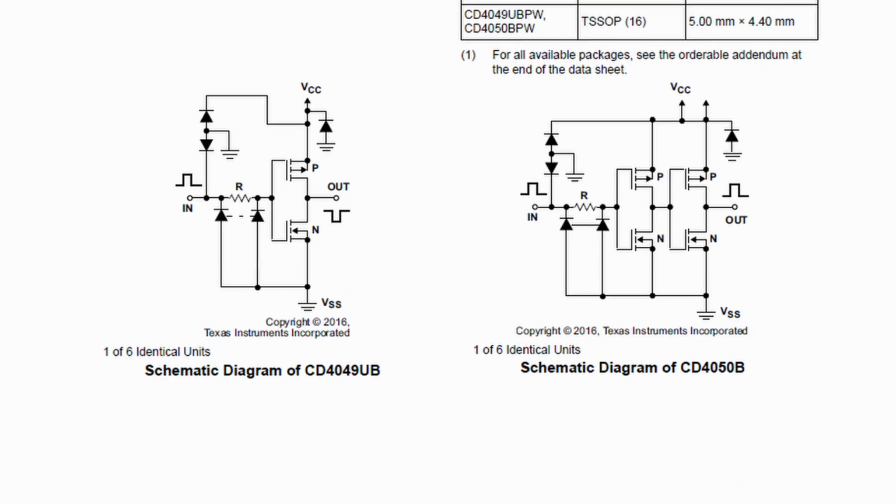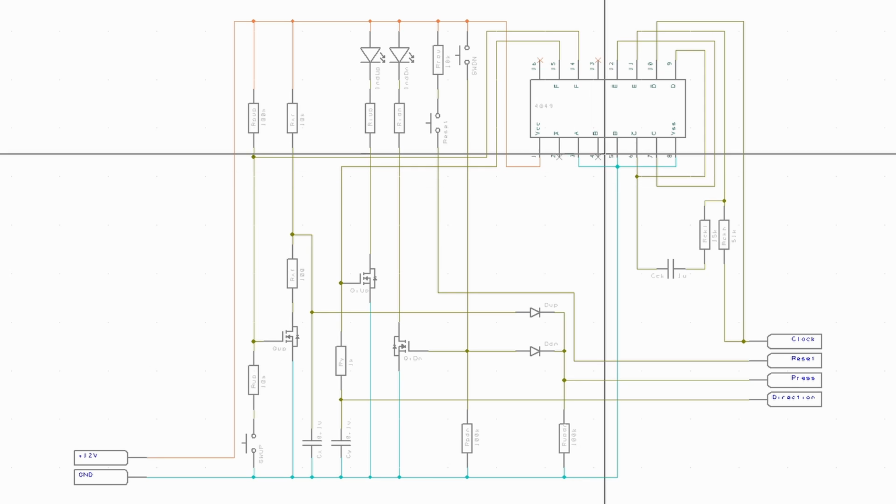Anyways, so now here we are today where I need yet another CMOS inverter, but that 4007 chip was totally used up in order to generate those three CMOS inverters. Well, it turns out there is another chip out there in the market that has six CMOS inverters in it, and it happens to be this one, the 4049. I also happen to have one. So I said, let's use this. So I put the 4049 chip in, and that means that I still have the three inverters that I had last time, but now I have three extra ones. So I used a fourth inverter, and now with this chip, I still have two empty slots that remain unused.